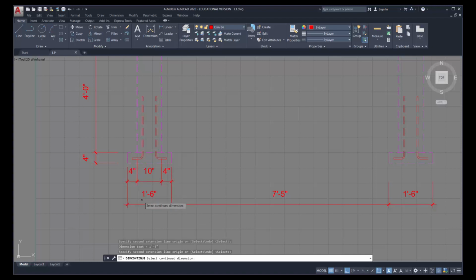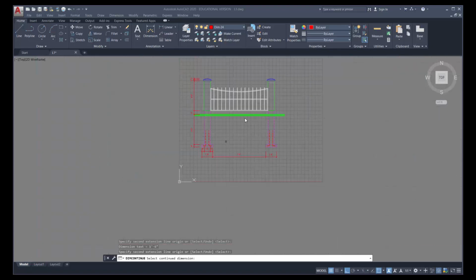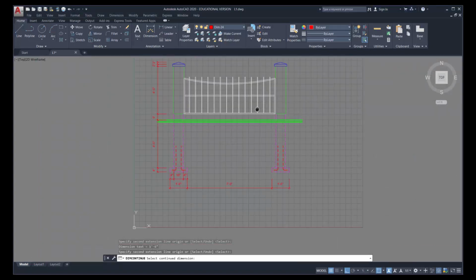And now we have this gap set exactly the way we've positioned it in our dimension style. So we've got an 1/8 inch gap, an 1/8 inch text, and an 1/8 inch to the next dimension line. That's our 3/8 inch baseline dimension setting. So sometimes students want me to repeat what I've done, and I'm going to be doing that with the fencing material up here.